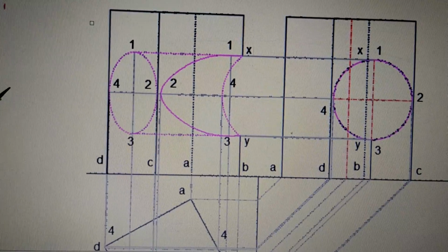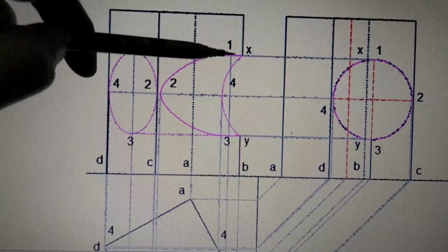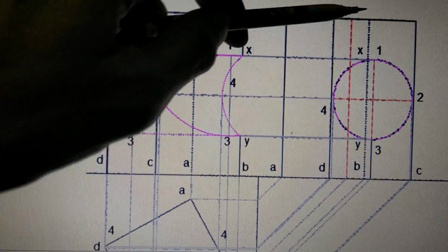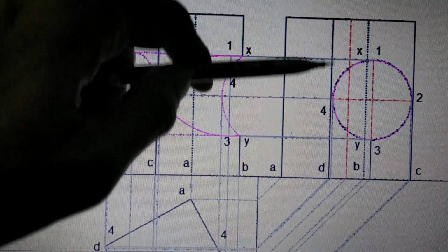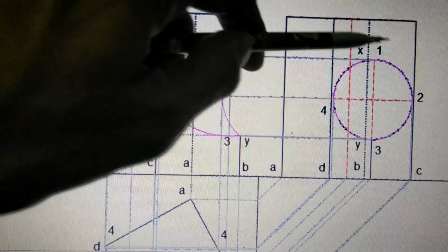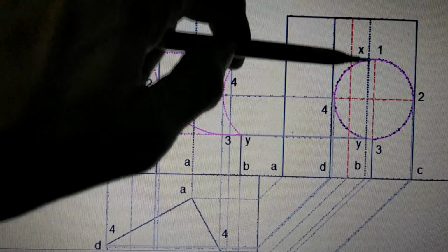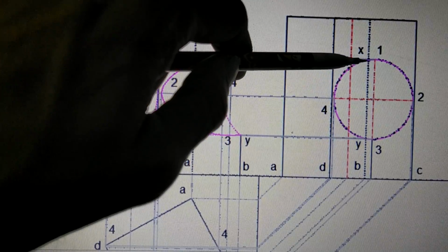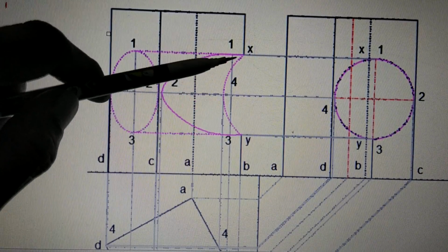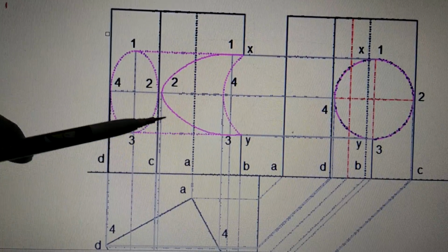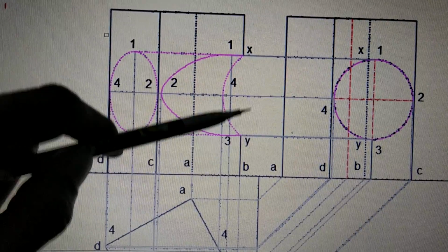Now again, one small thing to be noticed here, that when you draw these curves of intersection, where will be corners? Corners will be where there are corners here. So in this case, this is a circular hole, so no question of corner. But the vertical prism has got edges at 1, 2, 3 and 4. Out of that, at this B, the edge which is there at B, that edge is intersecting the hole at X and Y. That means at X and Y, because it is an edge, there is going to be a corner at X and Y. So according to that, we have drawn the curve, it comes like this, and then the next curve is like this, so that automatically a corner is created at X and Y.